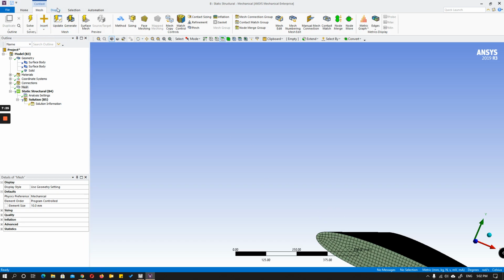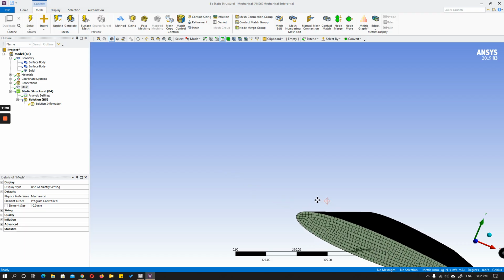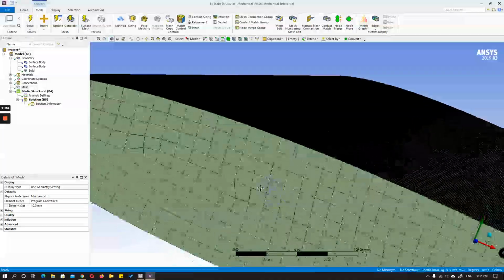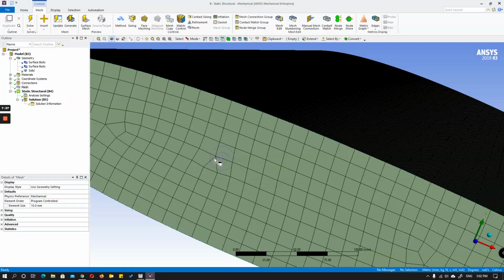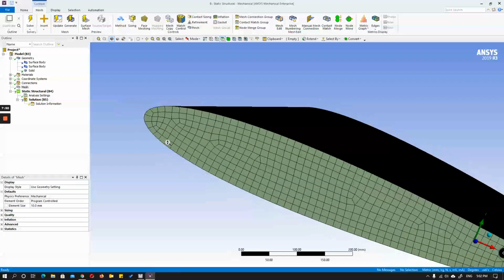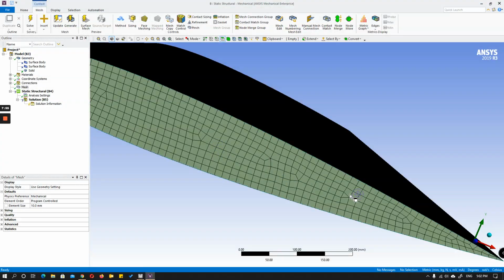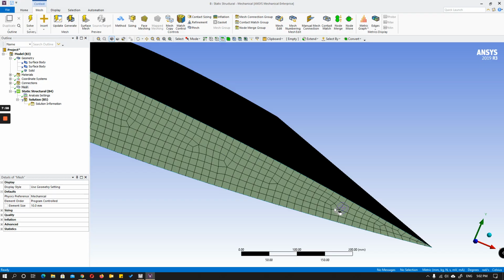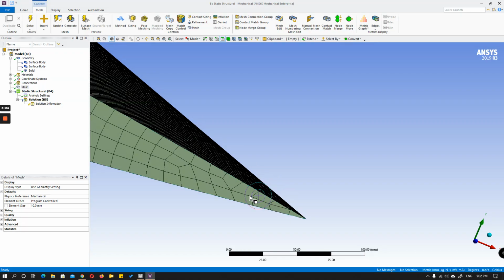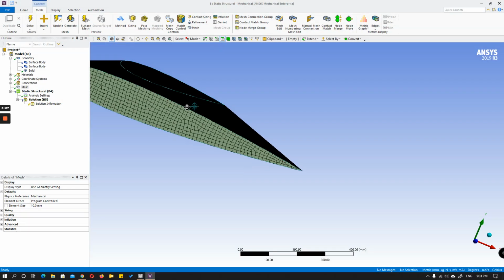And what I mean about using other software like HyperMesh is, from the general mesh that we did here, all are square boxes, but look here, we have a triangular element. This is not what we need. You can't call this a very good mesh. We need it to be just square boxes all throughout. Those kinds of things can be done if you are using HyperMesh. See, you can see a triangular one. This is not a triangular; it's a quad, but still, look at the shape. It's very uneven. See, take a look here. It became like this. You won't get enough proper data points here.